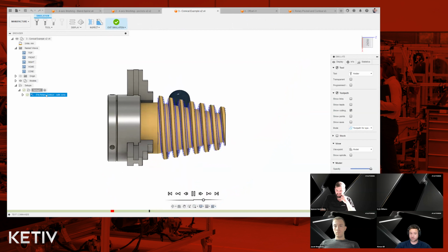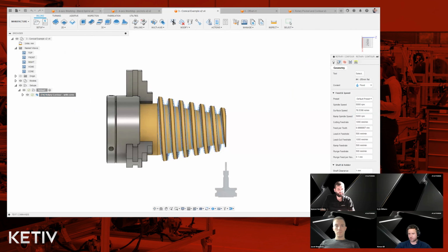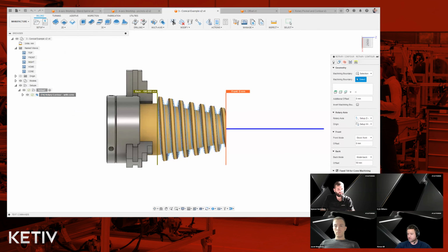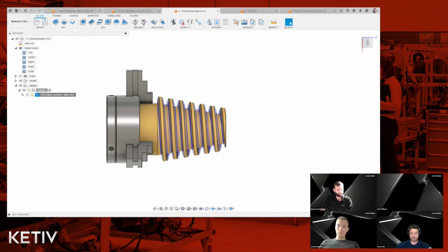All we do within the toolpath is define your fixed tilt for cone machining. In this case, it's a -5 degree angle, in which case it just tips that tool over 5 degrees in either the A or the B axis. So you end up with a beautiful surface finish on that conical wall. That's a benefit that some of the other technology we had just doesn't offer, but it does now.